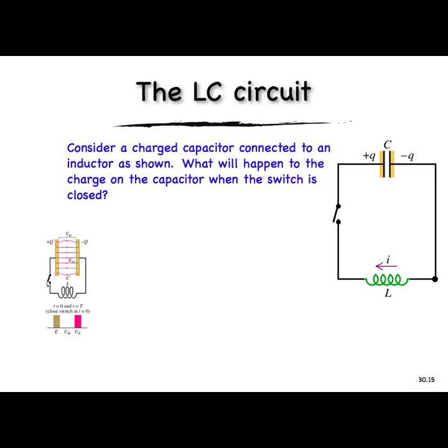So we can work out the rate at which the current will decay to 0. We look at Kirchhoff's rule around this loop. If the current's going left to right, we have a voltage drop of L times dI/dt across the inductor, and then a voltage drop of IR over here. And those voltage drops have to equal 0 because I go around a loop.